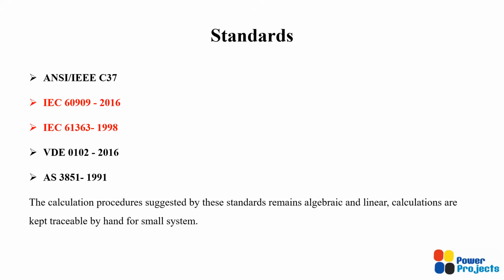There is another standard as well from IEC, which is 61363. Similarly, there are other standards like VDE, which is the European standard from Germany, and there is an IS standard. These are all the standards which are available. In addition to that, there are some country specific standards as well, something like a GOST standard. All these standards remain algebraic, and they are solving linear equations, and hence you might be able to perform your manual calculations as long as the system is small.